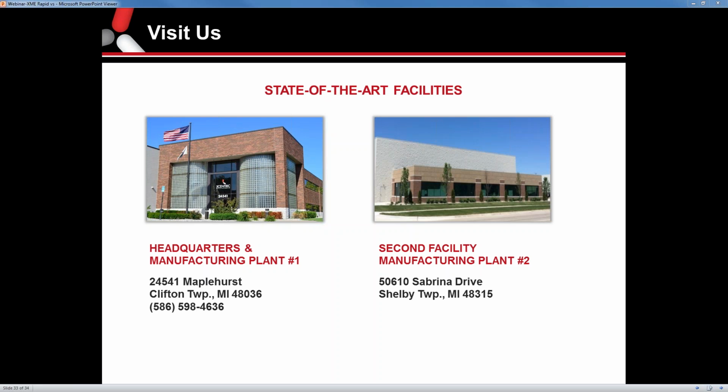Oh, sorry, we have one more question here coming up. Are your molds full aluminum, or do you use other materials for wear surfaces? Yes, in some tools where we have thin mold conditions, we will use steel or insert out with steel in the tool. And again, it's really going to depend on the end use of the part. If we know it's going to run 5,000 pieces versus 500 pieces, it may be built a little bit differently. And we may incorporate some steel into that mold.